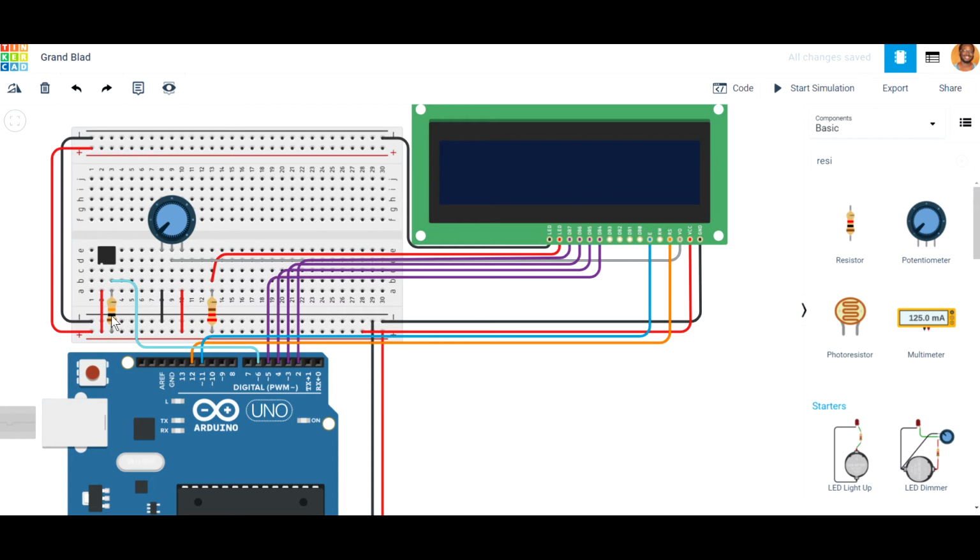So what's happening is when the switch is not closed, you've got the switch open, but you've got the 10 kilo ohm resistor on there taking care of any current going through the switch. Now, when the switch is closed, or you press the switch if it's a push button, in this case we've got a tilt switch, what happens is, because current prefers to flow through the least resistant path, the 5V will be connected through the wire, so it bypasses the 10 kilo ohms, through the wire to the input pin 6. So that completes the circuit diagram.